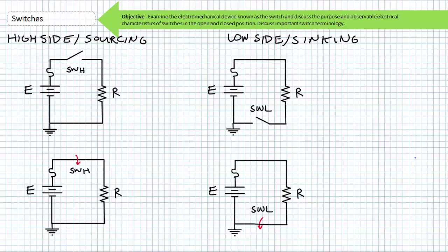Consider what would happen if an errant piece of conductive wire accidentally bridged the electrical load and something connected to ground at its bottom terminal. In this case, a whole lot of nothing would happen because that side of the electrical load is already touching ground via the intentionally grounded negative terminal on the source. The ground reference can be considered not a single point, but a large pool at the same potential. The operator can still start and stop the machine by closing and opening the switch.